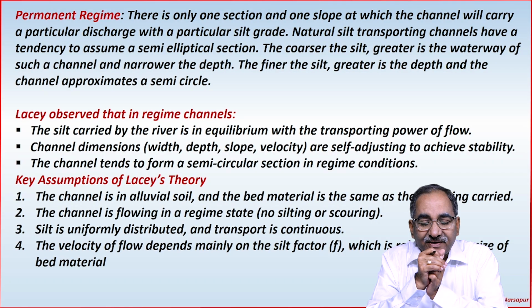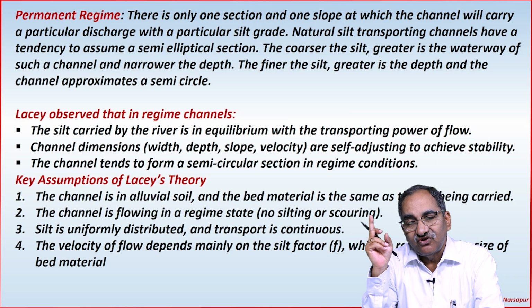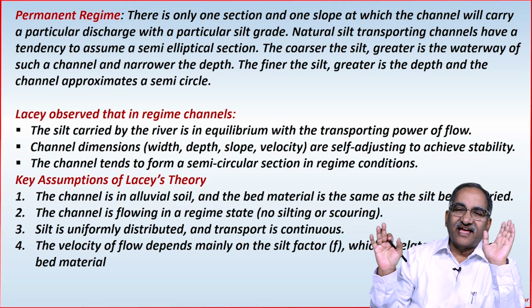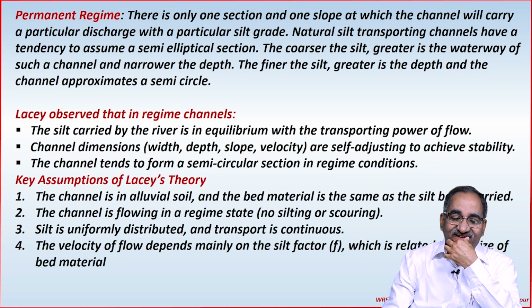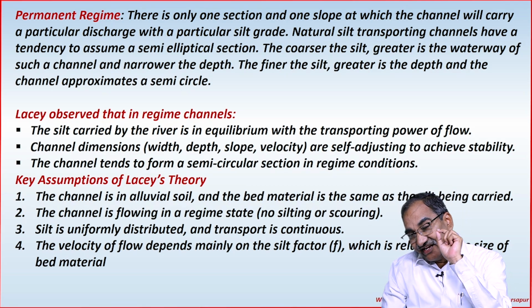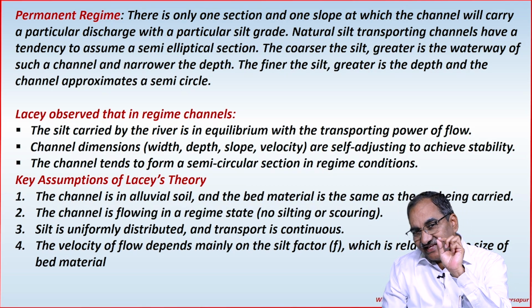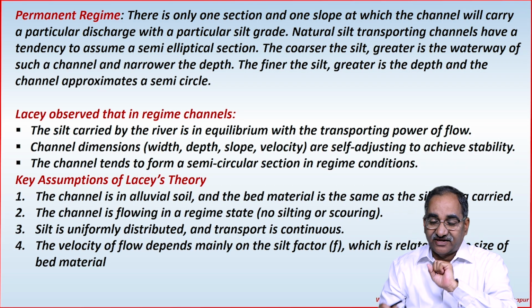What do you mean by permanent regime? There is only one section and one slope at which the channel will carry a particular discharge. That is what we are doing in the design, right? With a particular silt grade. Silt particle sizes are also the same sizes.